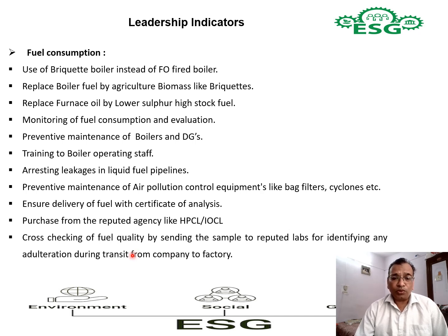So how do you know this? You can sample when the fuel container or tanker reaches your site. You have to carry out the sampling, and once in a while send it to a third party lab to ensure that the certificate of analysis matches that of the company which has been supplying. So this is all about the leadership indicators of fuel consumption.